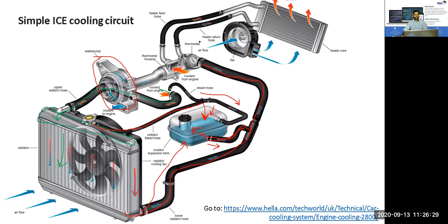As I was saying, showing on that schematic, there is this connection for the heater core. As you can see, coolant is going in this direction from the engine to the heater core, and returning from here. This is a blower. It is blowing air to the cabin, so through the little AC holes, the passengers are getting warm air.